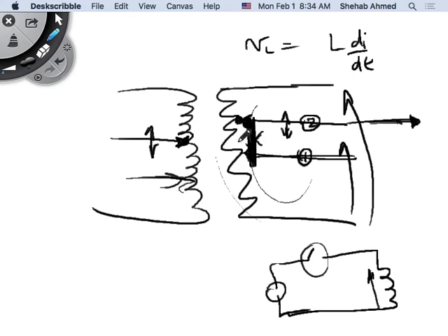Why? Because the insulation has to withstand, for example, these short circuits for a while until you make before you break, right? And then the oil may be more expensive because it's prone to these impurities being present. Of course, there's an automation system that goes along with moving this along, so it's a more expensive transformer. Can you live with it or not? In a residential neighborhood, maybe you don't care. If this is a major transformer feeding a huge chunk of the city, you don't have a choice. You will buy one of these more expensive transformers, right?